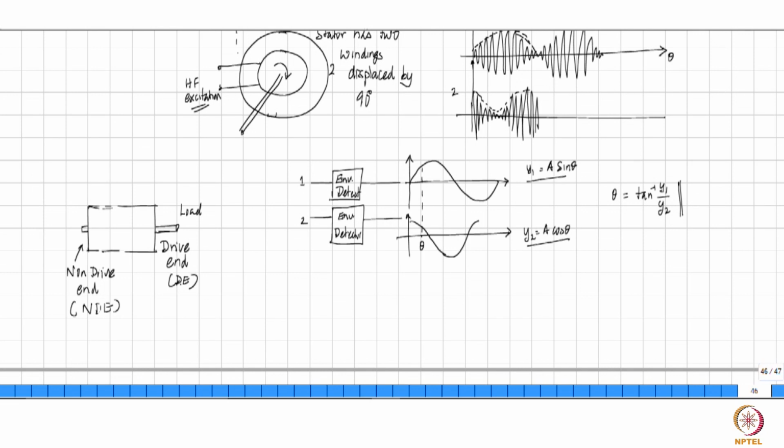And then you need to have an arrangement. The encoder obviously has to sit here. That will have its own shaft, and you make a mechanical connection. But you can't leave the encoder hanging like that at the end. There must be an arrangement to fix it appropriately, and therefore you need to have some arrangement that fixes the encoder onto the motor itself.